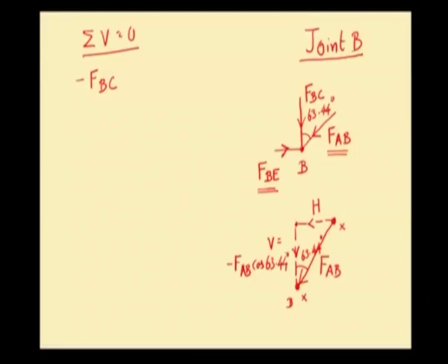Now, let us come to the horizontal component of FAB. Horizontal component of FAB moves towards left. So, according to our sign convention we are putting a minus sign. With respect to 63.44 degree, this horizontal component is opposite side of the right angle triangle. So, the horizontal component h will be minus FAB into sine of 63.44 degrees.